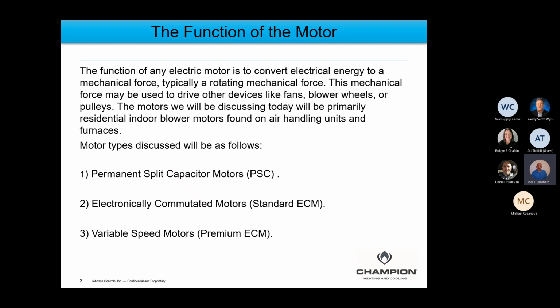And from a troubleshooting standpoint, you can take an ohm meter and take the module off of these ECM motors, and you can actually ohm the windings out. Now put this in your back pocket or write it down someplace. If you ohm out the windings of an ECM motor, you take the module off the back and be careful, let it discharge itself, let it sit for 5 or 10 minutes because there are some capacitors in there that can hold a charge.